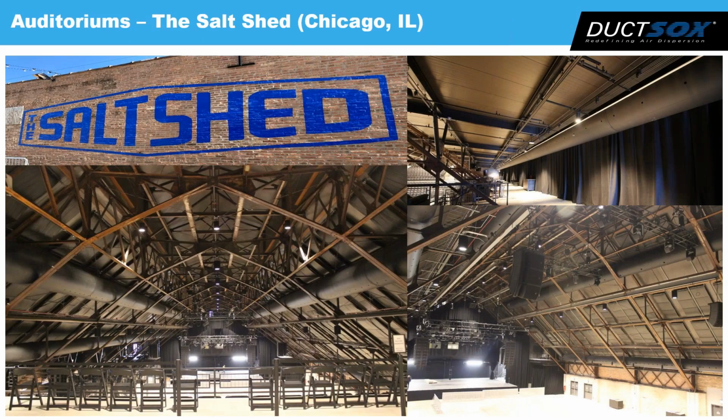We can also get very creative with retrofits and some tight spaces. So this is actually a job down in Chicago, Illinois, where it was a retrofit. They couldn't put anything on the roof and they couldn't hang anything from the roof because it's an old building that didn't have very good structure. So because this is such a lightweight product, they could use duct socks in lieu of metal, and they could run these right between those joists. There's maybe a quarter inch, half an inch, if that, between the joist and that duct. So we can run these in very tight spaces as well.